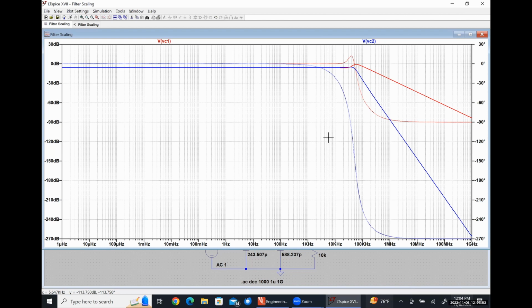Now, that being said, we made a passive network here meant to operate as a low pass filter. So it shouldn't have a whole lot of things going on. If this were a high Q bandpass filter, we might see something that would be worrisome. What we're going to be talking about later on this week will be active filters, meaning we're putting op amps and stuff in there to boost signals as well as filtering. And that's when we should probably start to be very diligent about component ratings and all of that kind of good stuff, because we're amplifying things. The whole point is to boost those signals, which might be in an unsafe-ish area.